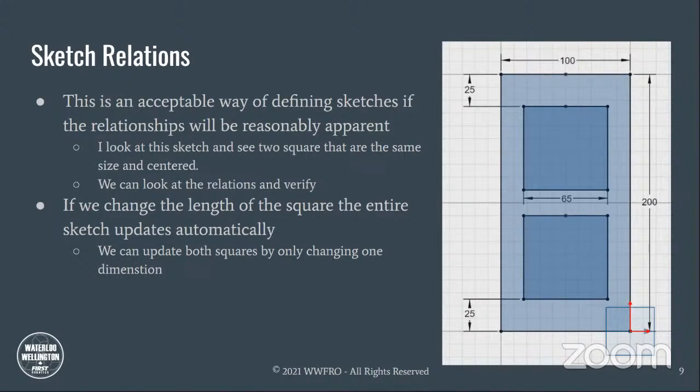And as far as design intent goes, I see one dimension and I see it's fully defined. So in my mind, I'd say whoever sketched this, they're going to make all those sides equal. I see some center marks on there, center lines, the little stars here. Little stars. I'll say, okay, they define center lines, so they're probably all horizontal to each other. I kind of know what's going on in the sketch with just looking at it.